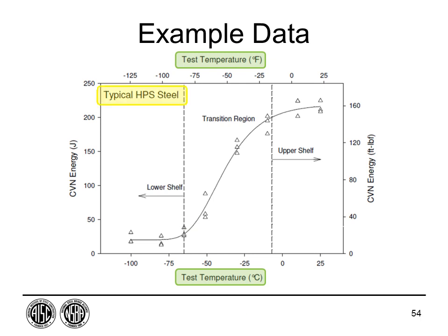What's interesting here is this is representative of some of the typical HPS grades that are routinely produced today. And I know you may not have context of toughness values for given temperatures. But I can tell you, zone 3 for bridges is minus 60 degrees, and around here, this is very good toughness for bridge steels to have. And it's routinely produced today by the mills. So we have much better steels than we had many years ago.